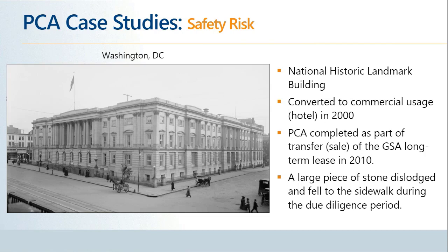There were also several incipient spalls or loose material that were noted on the stone facade. And based on the risk associated with both the loose material or incipient spalls as well as the spalls that were contained in the bird netting, which obviously isn't intended to function in that capacity, were immediately raised with both the seller and the buyer, and also with the actual building owner, GSA.